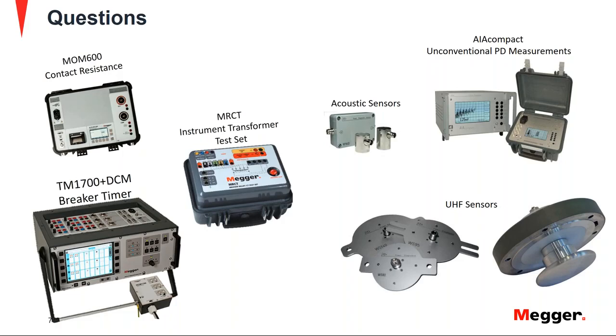All right. Next is over to Volney. Volney, the ferrites are inductors that are low impedance at 50 hertz or 60 hertz and high impedance at high frequency? Pretty much, but actually the ferrites are not inductors, they are ceramic. They are a ceramic material that acts as a magnet, so you can see it as the core of a transformer if you want to. Basically, at high frequencies, they will act as a high impedance.